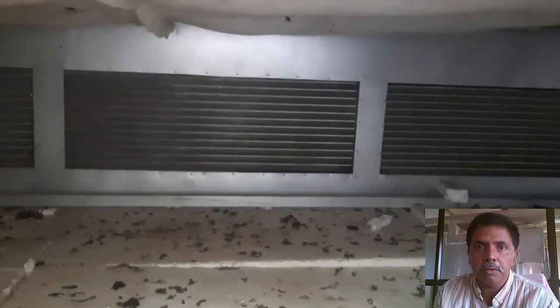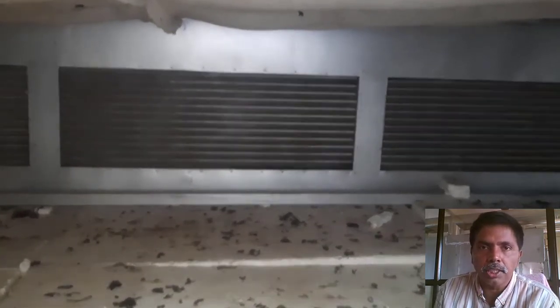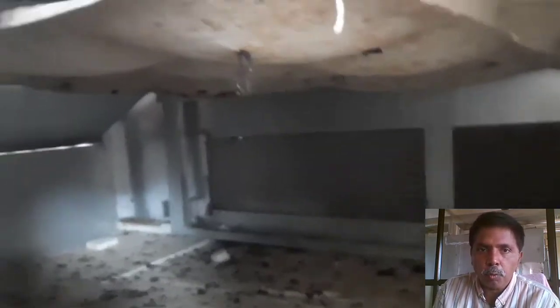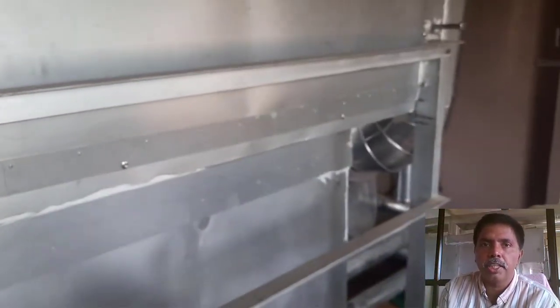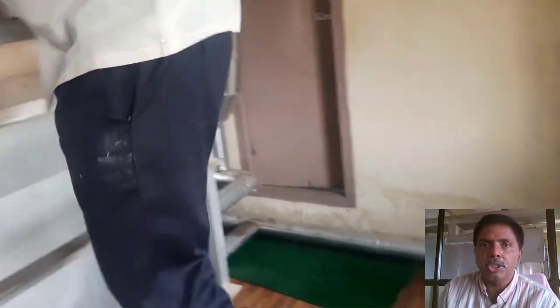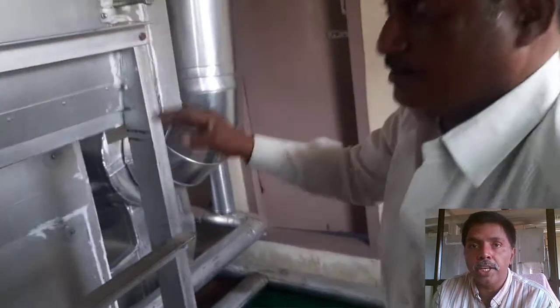In green chili itself we tested 4 to 5 types of green chili. It is not matching from one type to another type. Entire operating conditions are different. Some green chili skin thickness is high, some is low, so we can't fix it. This is the drying time, this is the mass flow rate of the air, this is the temperature of the air. After laboratory experiments only we can finalize the operating temperature of the air, the flow rate of the air, and how much drying time it will take.